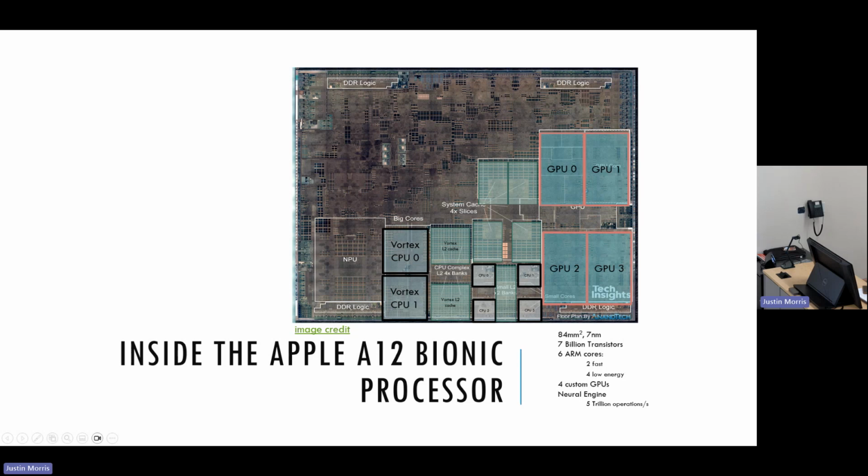Here we can also see they have these different smaller CPU cores, and they have this shared cache. And there are 4 more banks of cache that these GPU cores are also able to access. The rest of the die area is for interfacing with the lower levels of the memory, so DDR. So this is DRAM.